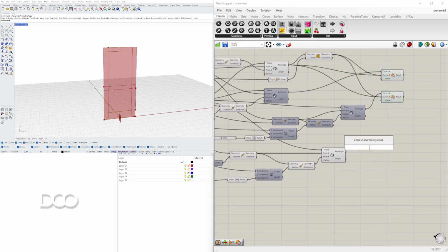Go to region difference, and this is what we want to keep, so that goes into A. We want to subtract the side rails, which are these two. I'll plug those into B. I'll hold down Shift and plug in an additional one.